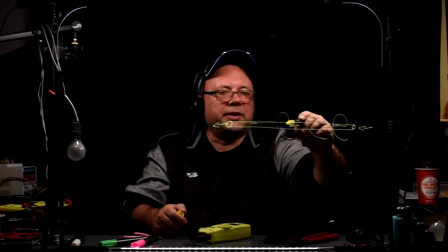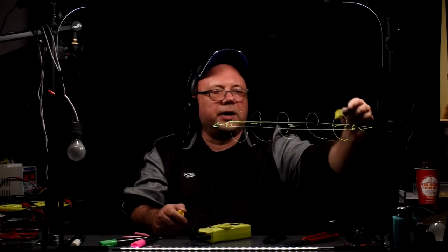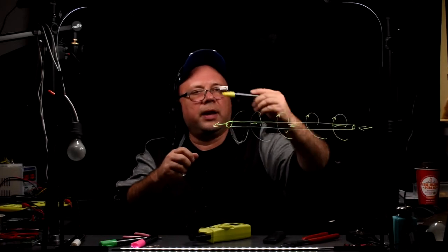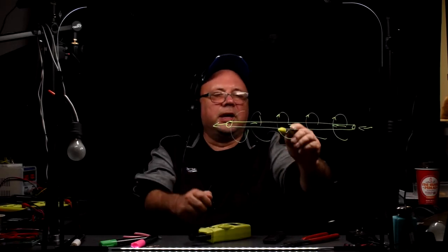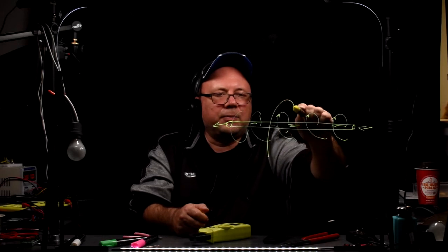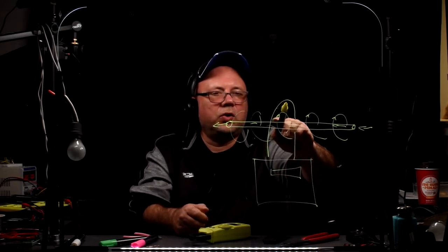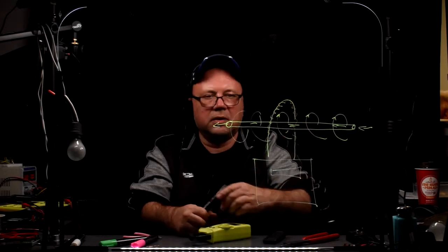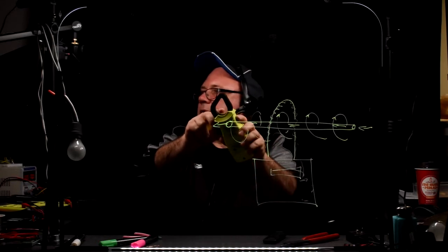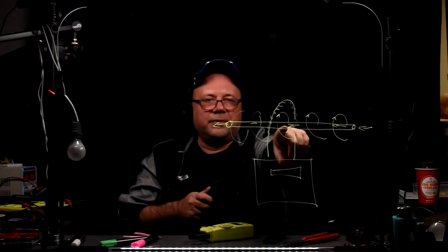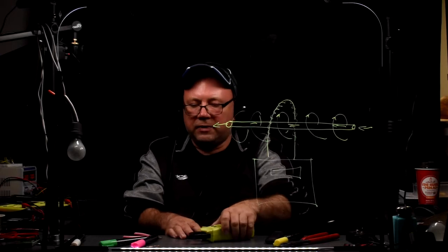If the current flows through this wire, you are going to have something called an electromagnetic field going around this wire, in a spiral way, just like a corkscrew. For the wine drinkers here, you turn the corkscrew, it goes that way, and the screw element moves that way. So that's the electromagnetic field. If you clamp on with the clamp-on meter, you're putting a coil around it. Here's a readout. The meter has a coil just right here. This is a sensing coil that is going to sense the strength of this electromagnetic field, and based on the strength of the electromagnetic field, it's going to do its calculations and display the value of the current. Pretty clever thing.